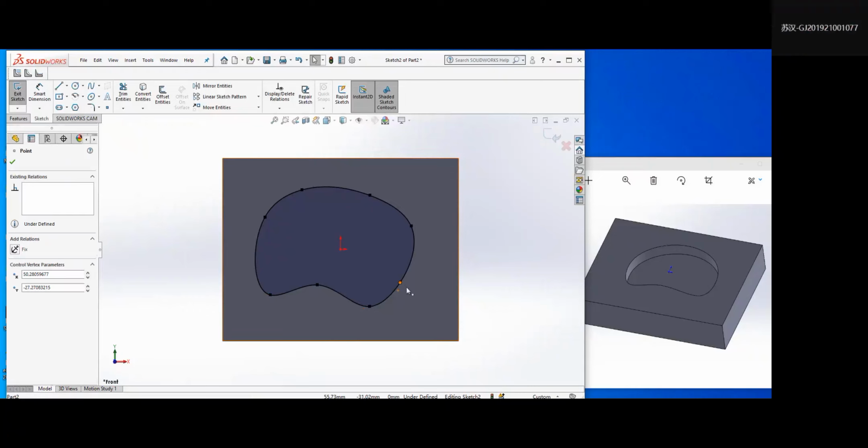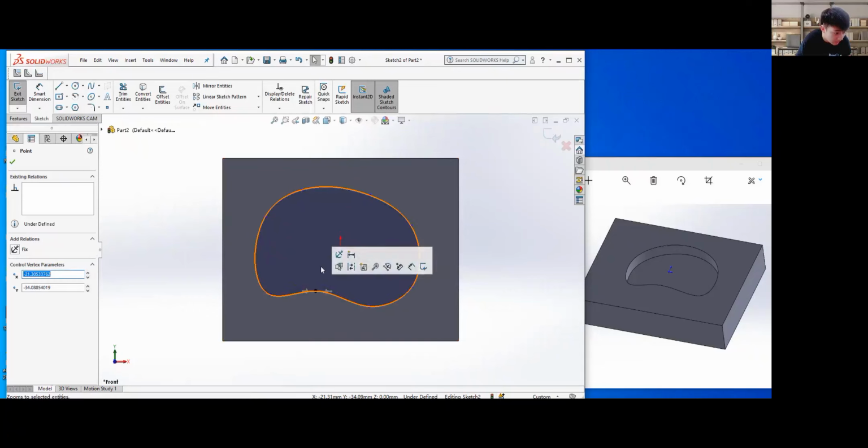All right. When you finish this spline drawing right here, you can move the points on it. Take care not to make it like this. Let me show you. Don't make it like this, because this angle, the curve here, is hard for us to mill.